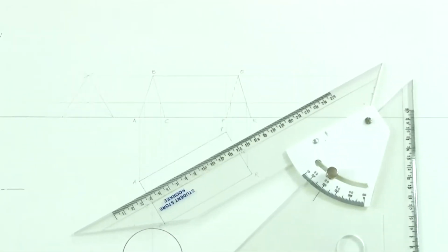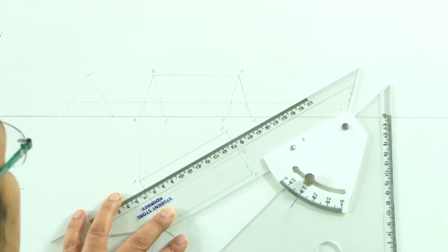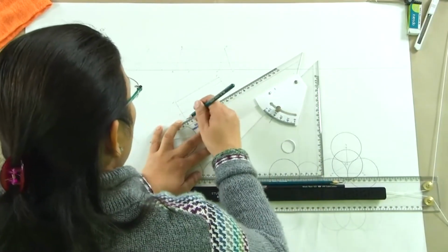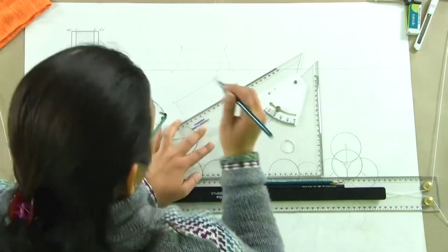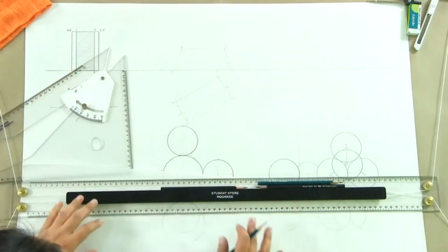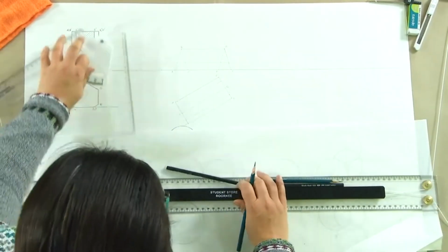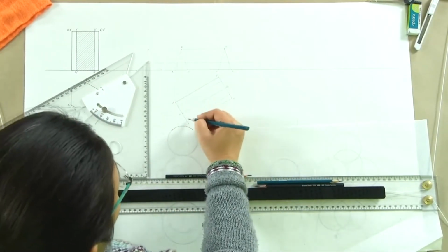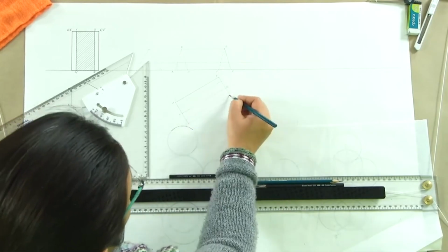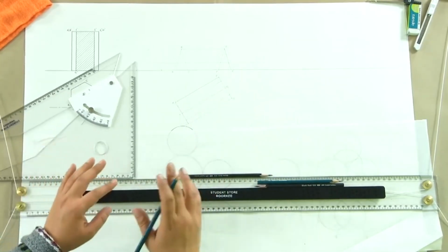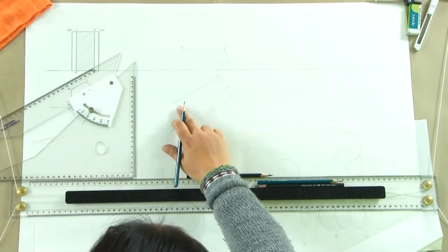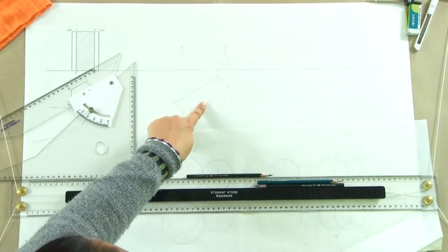And since the plane is parallel to HP, we will actually be getting the straight line here. Ideally, if your construction is right, if there is no flaw with your construction here, you should be getting the parallel lines. So, again, what we are seeing is that we are getting a rectangular section here. It is a prism, and since the plane is parallel to its axis, we will always be seeing this rectangle here, which is exactly what we are seeing.